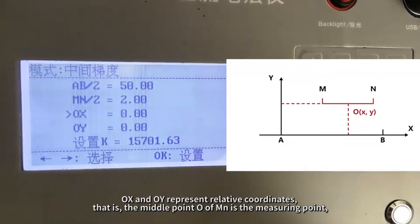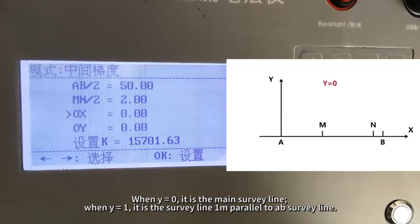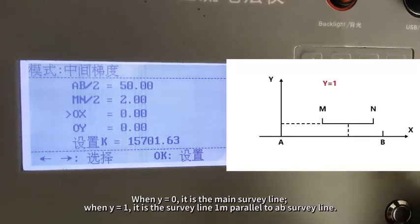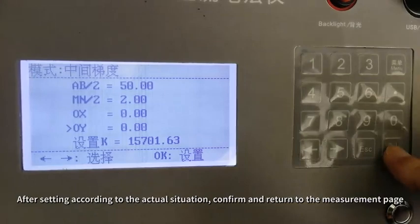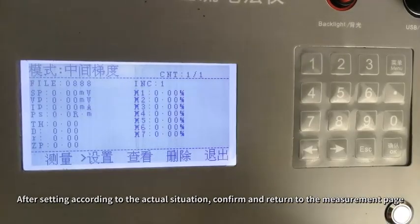O x and O y represent relative coordinates, that is, the middle point O of MN is the measuring point. AB is the x-axis of the coordinate axis, and the y-axis data is the parallel distance between MN and AB survey line. When y equals 0, it is the main survey line. When y equals 1, it is the survey line 1 m parallel to AB survey line. After setting according to the actual situation, confirm and return to the measurement page.